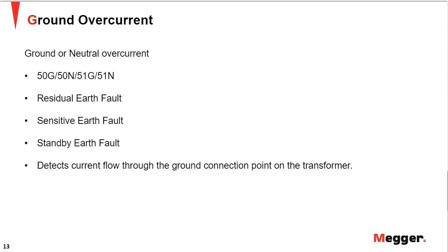In this particular relay, it uses a ring CT, what you call a core balance CT, around the 3-phase conductors, and the relay connected to that will detect a very low ground fault current. You could have a setting set really low, as low as 1% of FLA. And again, the time coordination for these relays with the downstream is very important.